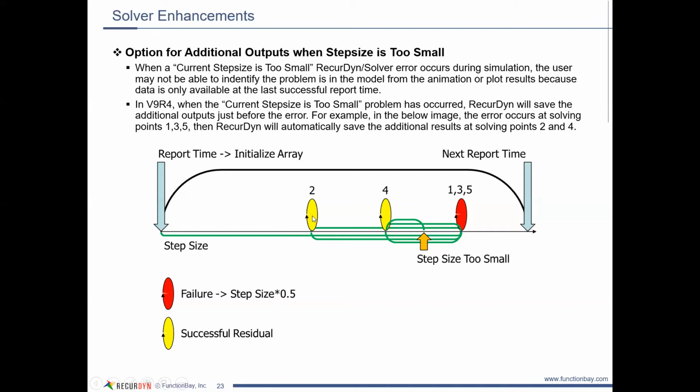So then it's like, okay, I took this size of step, it converged, I'll take another step of that same size. And this is try number 3. Once again, there's something about maybe this point in time where something is amiss. So substep 3 also fails.